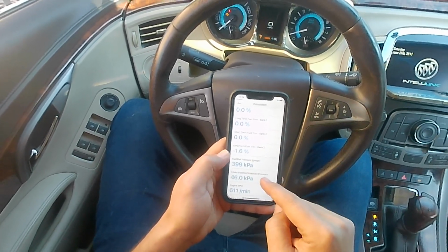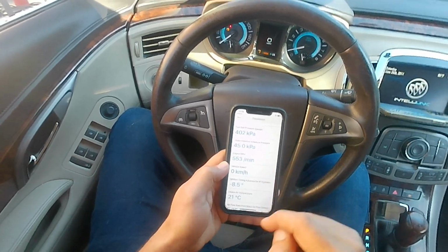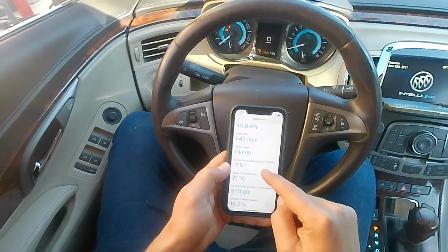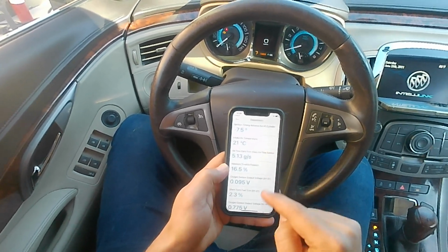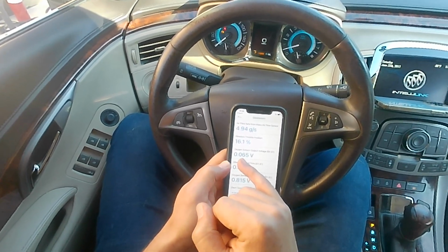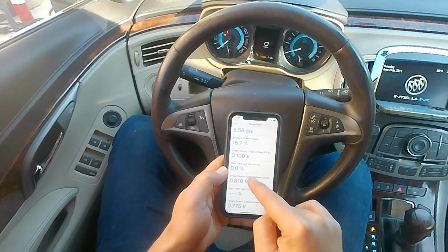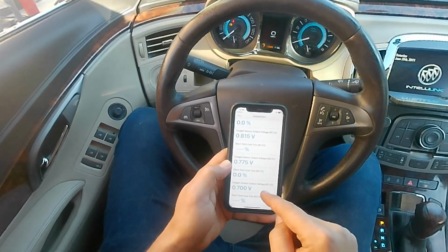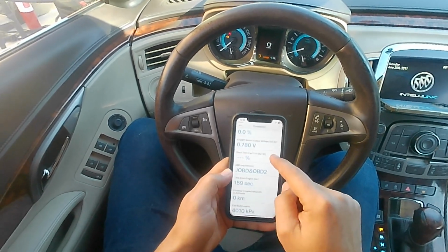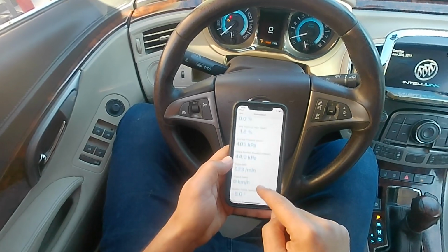So let's just leave this aside now, and take an overall look at the intake manifold throttle, and engine RPM is fluctuating. What I'm gonna look at is the oxygen sensors here. This is bank 1 S1, and then we have the other one, bank 1 S2. I want you to take a note of these two oxygen sensors. This vehicle has 4 of them, and here's another oxygen sensor on bank 2, and this one is bank 2 as well. So we have 4 oxygen sensor readings going on here.